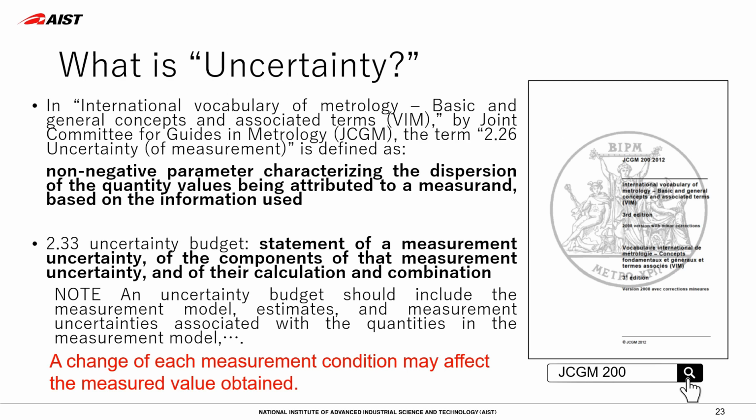If I give you an example, in antenna measurement, the antenna separation is decided to be 3.0 meters. For example, we locate the receiving antenna 3 meters away from the transmitting antenna by using a measuring tape. However, the separation is not always exactly 3.0000 meters. Assuming the estimated possible error in the separation is 10 millimeters, that's the assumption, the site attenuation may vary in terms of the probability distribution of the separation error. This is the uncertainty associated with the antenna separation.